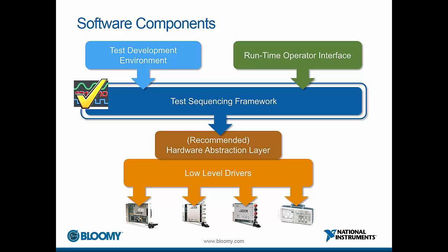Device interactions should be implemented as part of a hardware abstraction layer. Here, individual driver functionalities can be combined to create more complex capabilities. It is a good idea to abstract the channel and instrument signal names out into human-readable aliases. These aliases should be test-specific, allowing the developer to understand the signals from the unit under test's point of view, rather than the instrument's point of view.